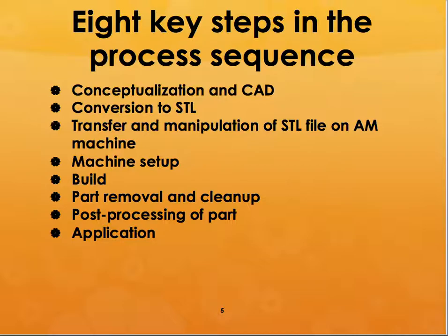So you have to make the software and the machine understand and set up the amount of information that it needs in order to build the part. And then after that, it has to build the part. Then you have to remove the part from the build envelope. The inside of that machine is called the envelope, so you know how much volume it has, so you can define the maximum size of the part that you're going to be building.